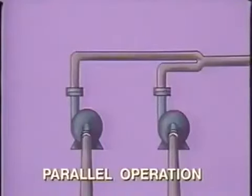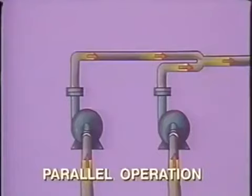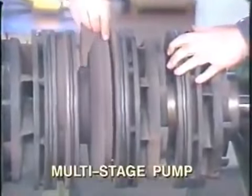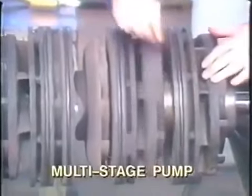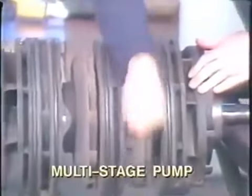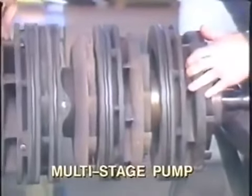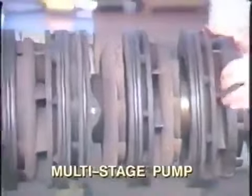They may also be set up in parallel where both pumps have a common discharge. This arrangement is used when an increase in volume is required. A multi-stage pump may be used when higher discharge pressures are required. This pump is like several single-stage pumps operated in series, but the impellers are mounted on a common shaft and enclosed in one casing.